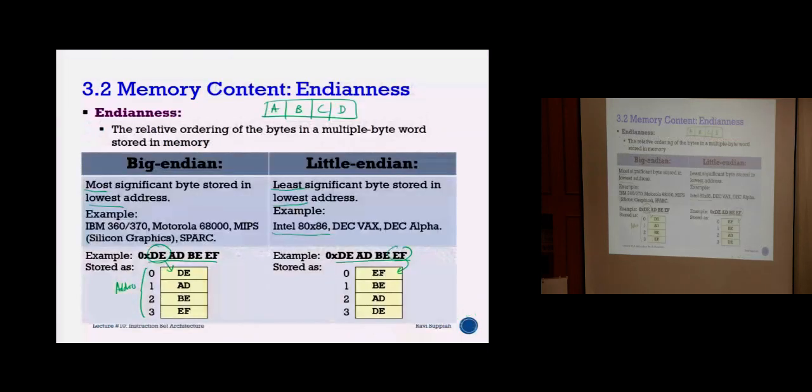Then we talked about the Endianness of your data. This is very critical when you have multiple bytes of data representing a larger word. If I have a word which is 32-bit, and I have 4 bytes of data, how is this data arranged? This plays a significant role when you deal with different boards.